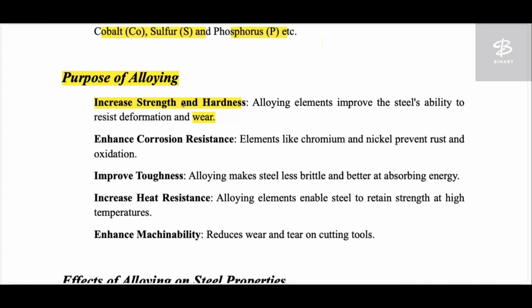Okay. So what is the strength? Strength means they will resist the applied load, before breaking, before failure. So before failure, how much load a material can sustain is known as strength. If we talk about hardness, I have already taught you the definition of hardness. I mean the surface of a material is not going to respond when you scratch it. It means there is some kind of resistant property over the surface, so that a scratch is not allowed over the material. That is hardness.